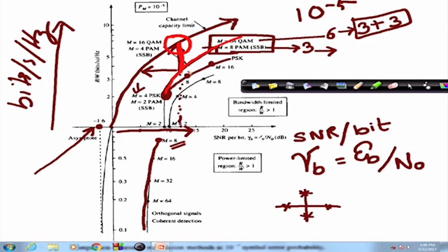If we want to see the capacity gap with PSK, we have to refer to this particular curve, and similarly for M-ary orthogonal signals, of course, how this curve extends there is what we have to see. The other way of viewing this curve would be that given a particular spectral efficiency, what is the excess amount of Eb/N0 required to achieve that.